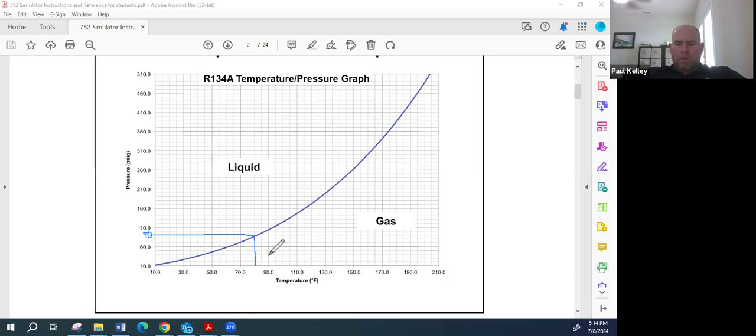Sometimes it's not 100%. Sometimes there are cars with moisture and air in them, and that will make a pressure. So it would say that there's pressure in the system, but there might not be enough refrigerant. But that's kind of rare. So generally, if you hook up gauges to a car and it reads around what it should on this chart, you can tell whether it's charged or not. Now, let's say it's a little more extreme. Let's say it's like 100. If you look, 100 would go to here, 100 would go over. 100 outside would be like 110, 120, almost 130.